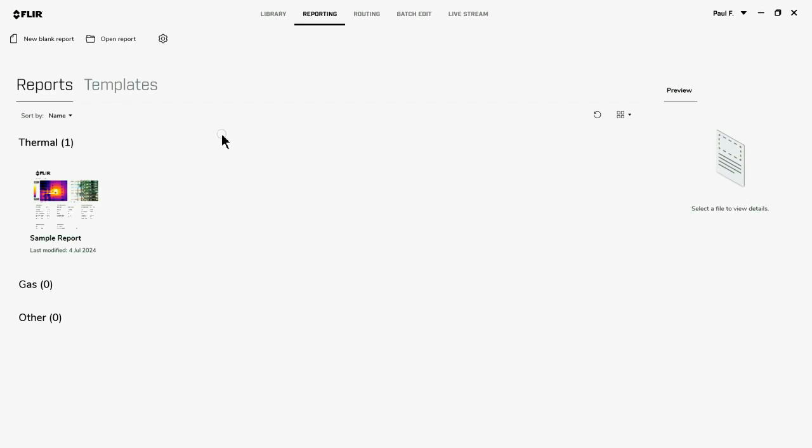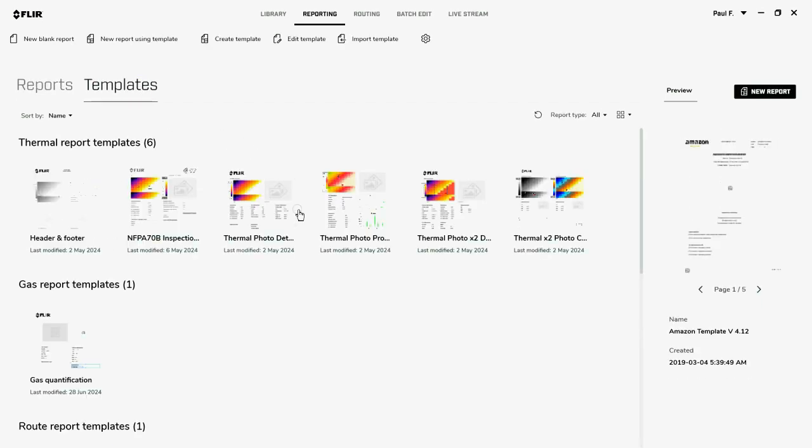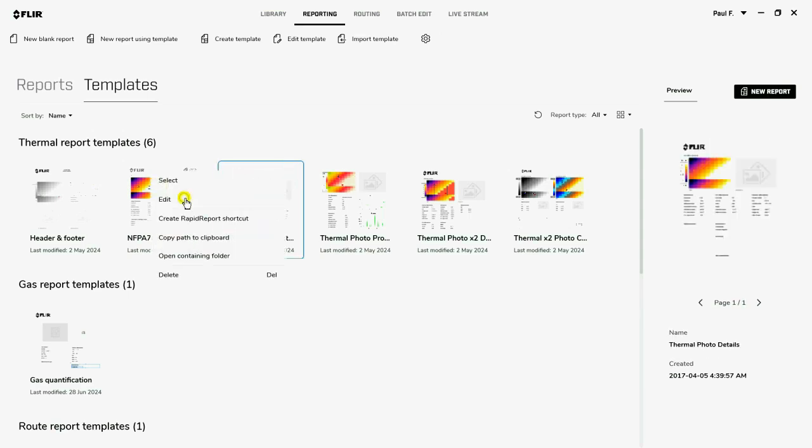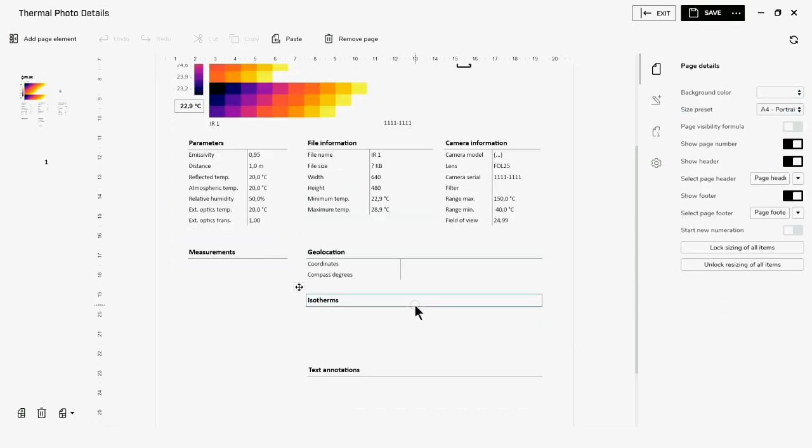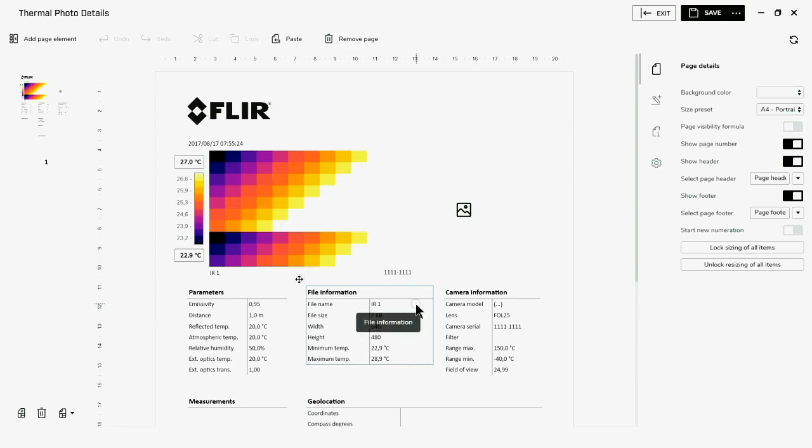Before designing your own template, it is suggested that you might review some of the installed templates that came with Thermal Studio. One of them may have a majority of the options that you would like in a report, and it would be a simple matter of editing that particular template. Choose a template, right-click on it, edit it, and review whether the contents of this particular analysis page are of your liking. One thing to note, as mentioned earlier, the default page size is A4.